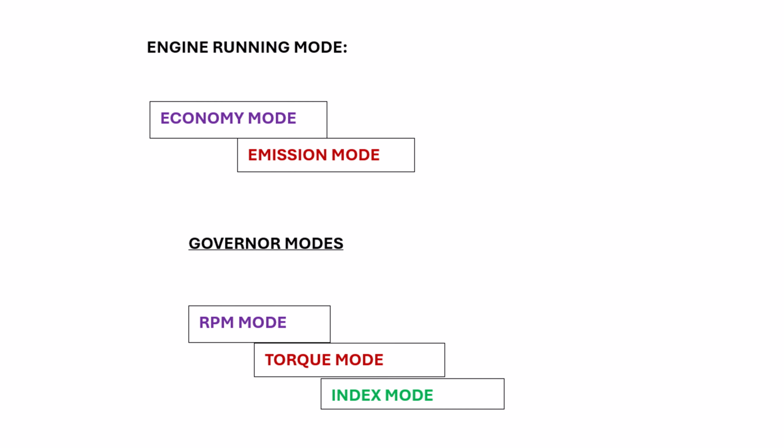increase the RPM, provided each RPM has a certain amount of fuel which can go. If within that amount of fuel which can be released, controlled by the torque mode, because torque mode acts as a limiter, for each RPM only so much fuel will be released.